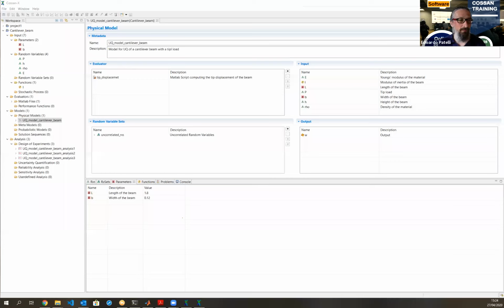That's good. Yeah, I suggest we move to the design of experiment using quasi-Monte Carlo simulation, because that's linked with Monte Carlo. Absolutely. So, what is the difference between the design of experiment and the Monte Carlo analysis? In the design of experiment, we are only evaluating some fixed deterministic points that are created with fixed deterministic rules. When you do uncertainty quantification, it might be more meaningful to actually let the randomness evolve as it should evolve. That means completely random or quasi-completely random.